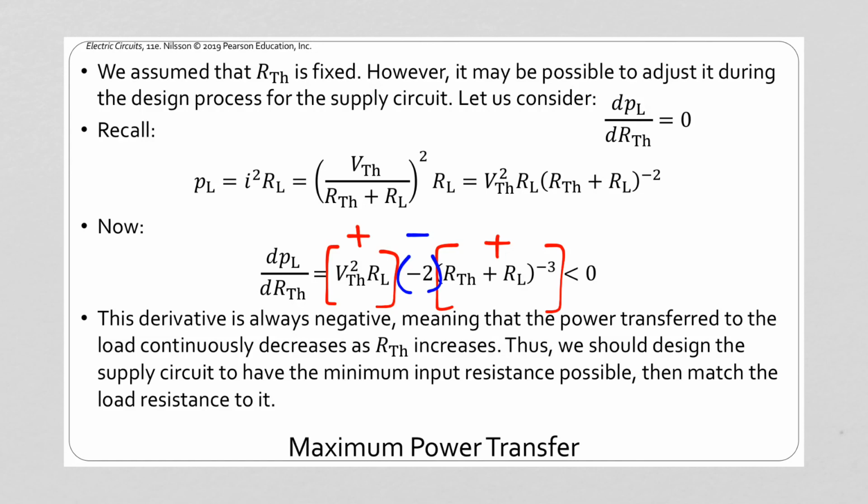The only exception to this is perhaps there's an industry standard that kind of splits the difference, where there's an industry standard output or Thevenin equivalent resistance that you'd want to match your industry standard load resistance to, to make sure that you'd have interchangeability between systems.